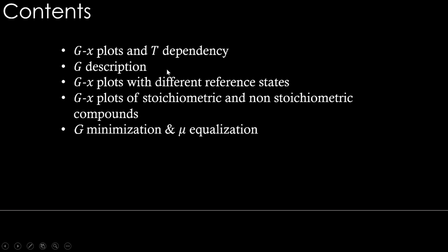These are the contents. We'll see how Gibbs energy versus composition plots change as temperature changes, and we'll see the mathematical descriptions of these Gibbs energy curves. And we'll see Gibbs energy composition plots with respect to different reference states, and how the curves look for stoichiometric and non-stoichiometric compounds, and how Gibbs energy minimization and mu equalization are the same.